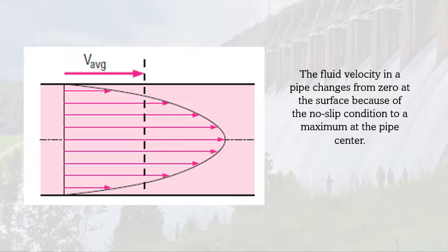The average velocity in heating and cooling applications may change somewhat because of the changes in density with temperature. But in practice, we evaluate the fluid properties at some average temperature and treat them as constants. The convenience of working with constant properties usually more than justifies the slight loss in accuracy.